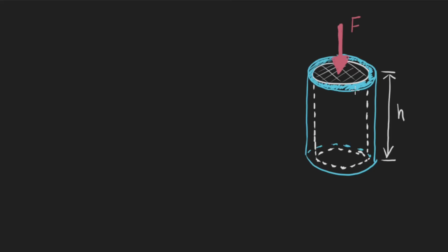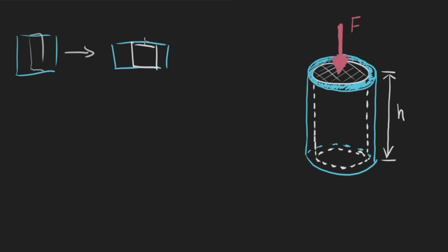So if they're welded, glued, stuck together, then what's going to happen? If I think in a 2D case, I'm going to have my outer right here, and my inner part right here, and then I'm going to compress it. So it's going to get smaller, maybe it'll get wider. It's going to look like this. But if it's glued together, then I'm going to assume that the heights of these are going to be the same, which means that the delta of, we'll just call this the inner, has to equal the delta of the outer right here.